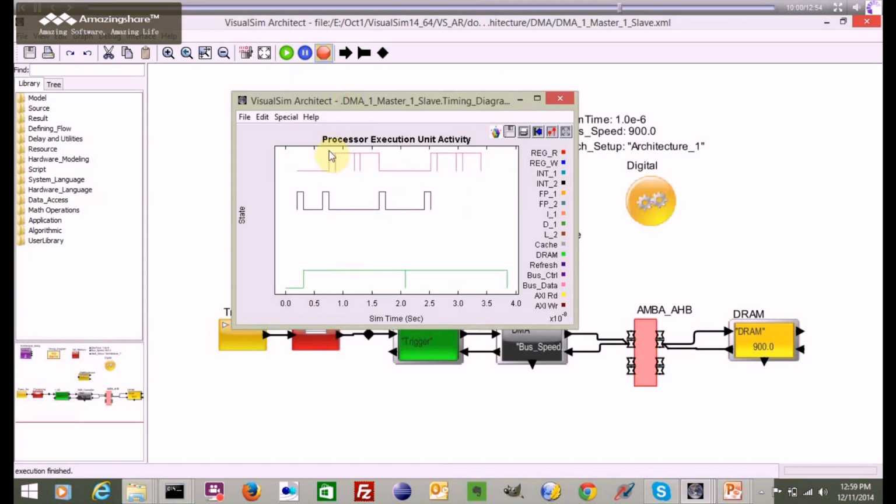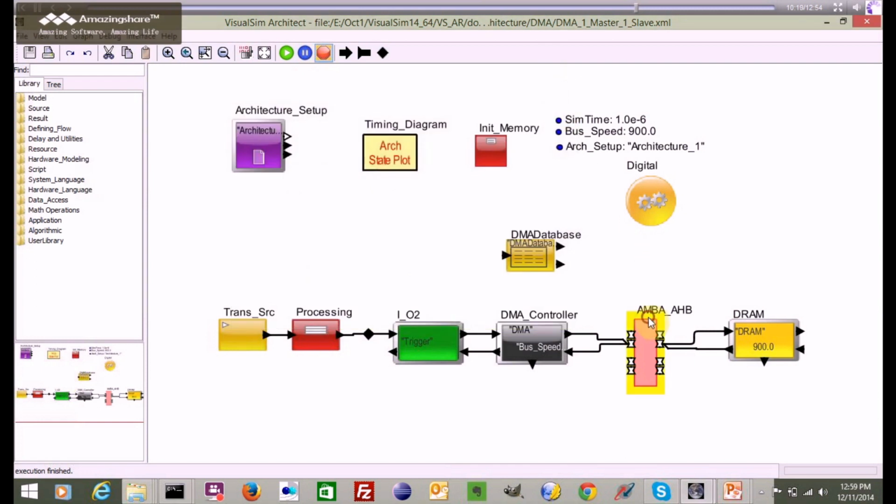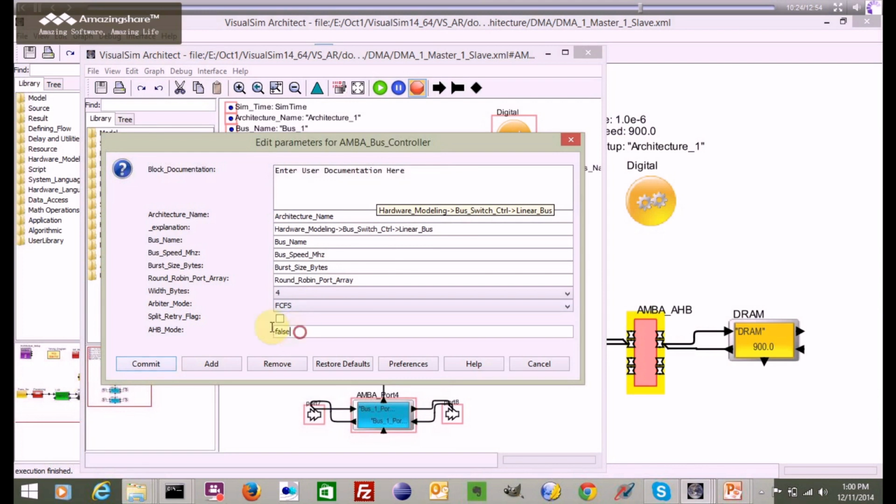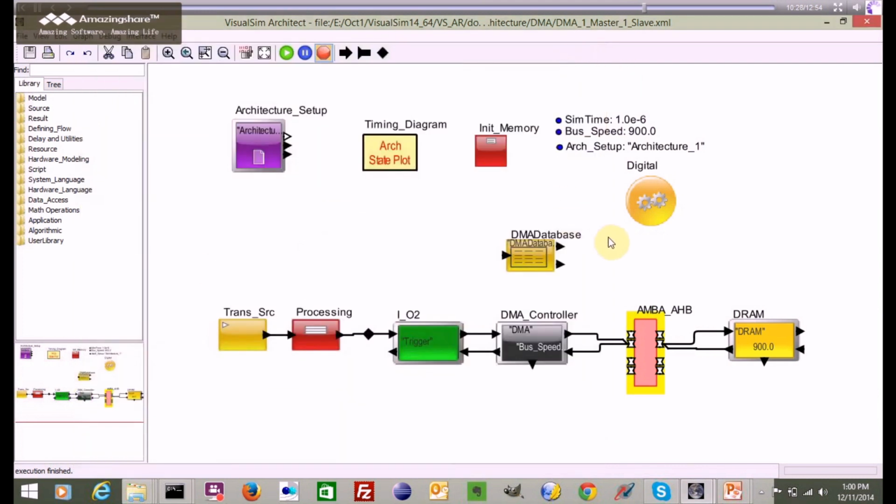see here the first fragment from the DMA is actually of 32 bytes and is again fragmented into two parts of 16 bytes each by the AHB block. By default, we send the transaction as it is to the output port in AHB block.